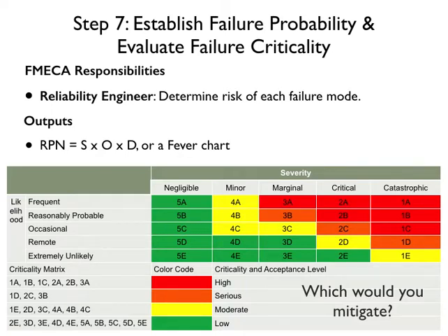So instead of having a more detailed value for the risk, as you would in an RPN, this is presenting it in a slightly more binned way. For example, if a failure mode's severity is negligible, regardless of what the probability is, the risk level is low. And that's what you see by the green on the far left side of the chart.